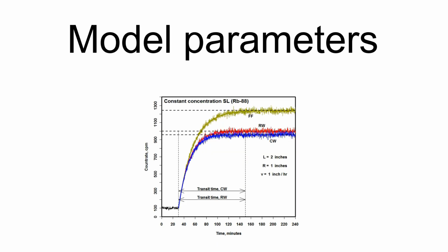The parameters used in these models are summarized in this list. Time interval, T, time, measured from start of concentration step. Concentration, Q0, activity/volume, assumed constant over the interval. Decay constant, lambda, 1/time, for the specified nuclide. Media collection/retention efficiency, kappa, implicitly includes line loss.